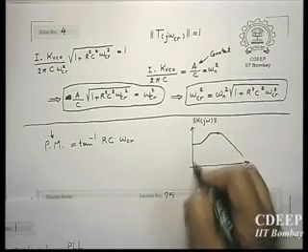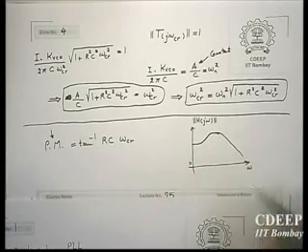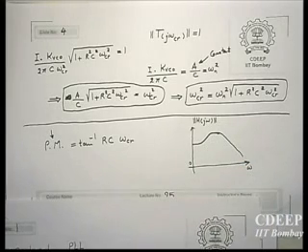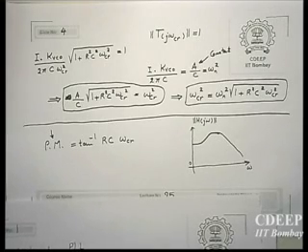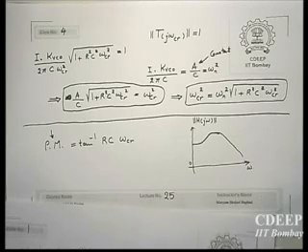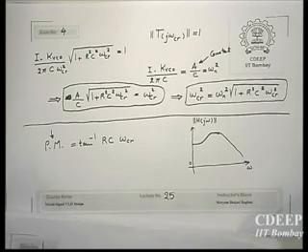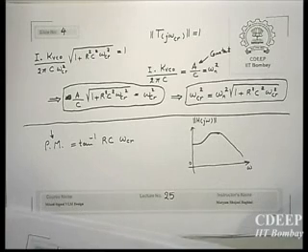Because suppose you want to use this PLL as a demodulator, now at some particular frequency it has a different gain, and therefore you get nonlinearity. It is easily a nonlinear demodulator. So these are some of the problems. Therefore that's why we usually don't go with a very high zeta. These are other problems with this kind of transfer function.